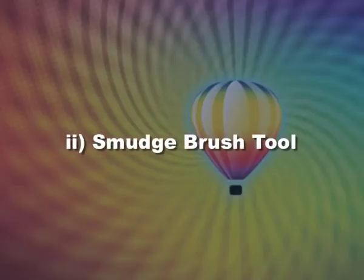2. Smudge brush tool. In the Shape tool, another option is available, which is the Smudge brush tool, and to use this option, again you need to draw a box or any shape. Fill a color of your choice. To apply the effect of this tool, necessarily it has to be converted to curves. Convert to curves means converting your drawing into an object. It can be text also, it can be a circle or triangle, etc. After which its attributes are changed into an object.